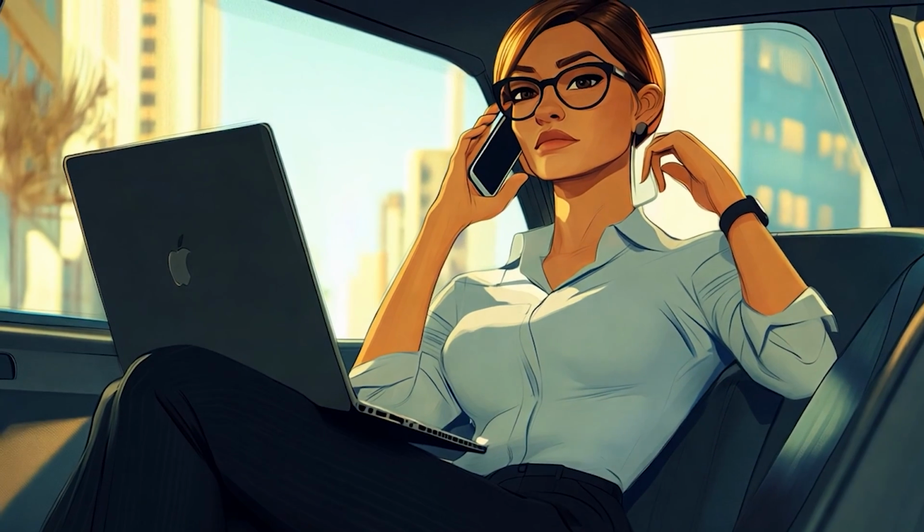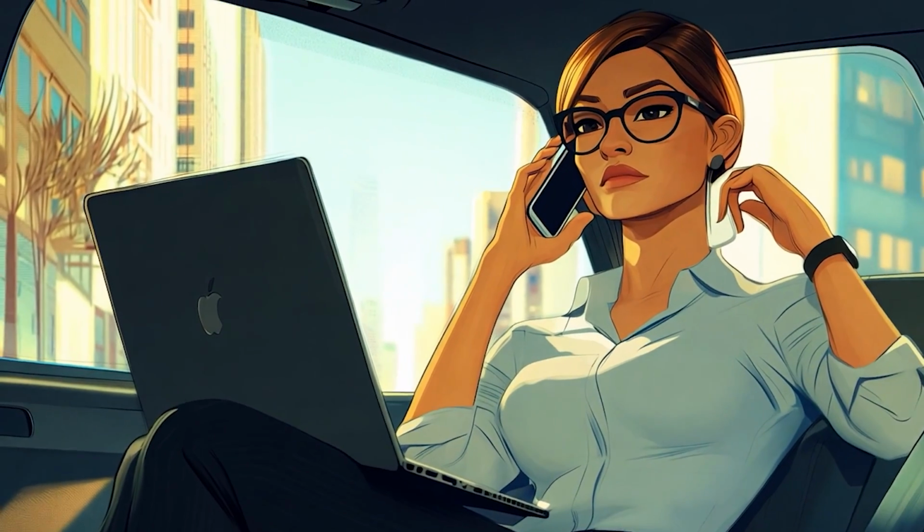The client just called. They want us to add a microclimate analysis to the presentation. Now let's talk about microclimate analysis. This is really an important step for you to understand how your design interacts with the environment. And Forma automatically pulls local weather data into your model to evaluate things like airflow, humidity, temperature. And with that, it allows you to understand how your building performs in terms of, for example, outdoor comfort, which is basically a perceived temperature.